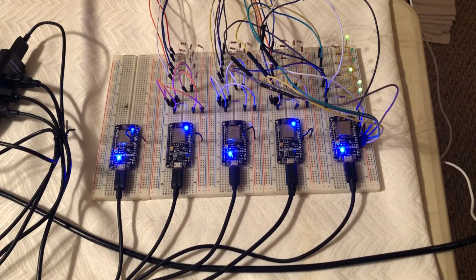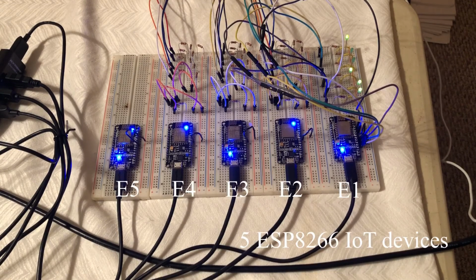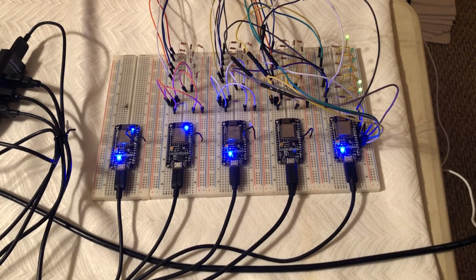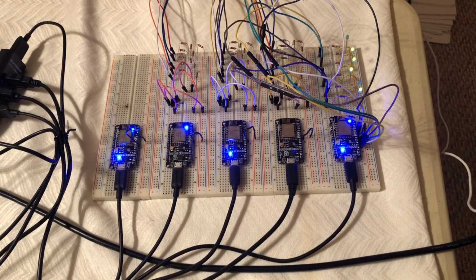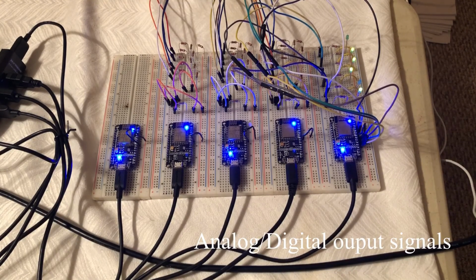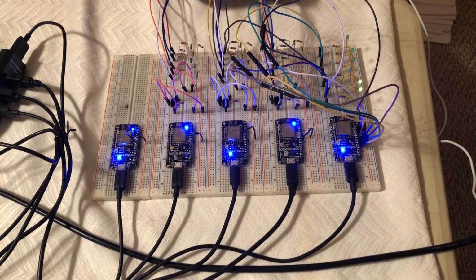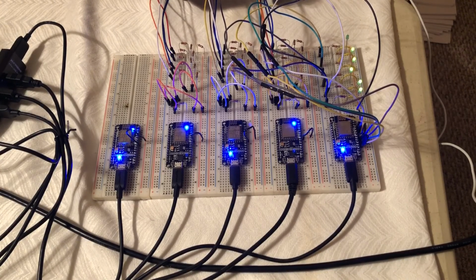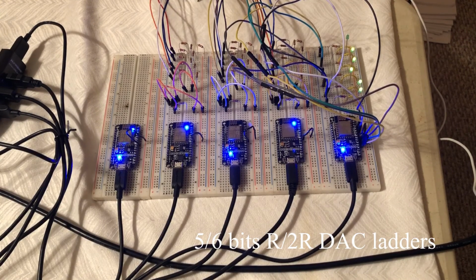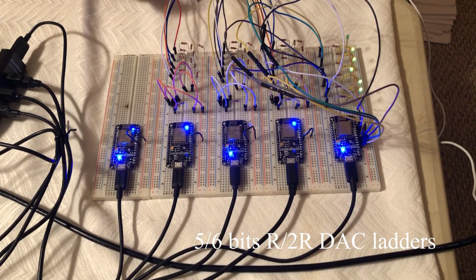At the hardware level, the system is made of 5 ESP8266, and based on the simulation we showed on the GUI, the elements are encoded either in digital in 1 bit, 6 bit or 5 bits digital values, and we write the values accordingly depending on the subdivision that we chose. So we use the analog outputs of the ESP8266. We also use the digital outputs, and here we have two implementation of R2R layers for DAC conversion, because we have some loads that we encoded in 6 bits values, and here we have one implementation of R2R layers for a 5-bit input.